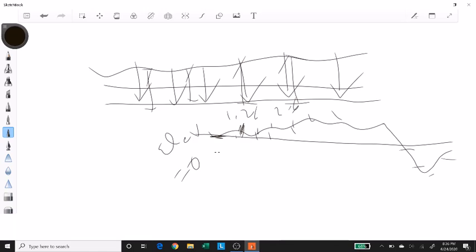And usually this reference is used as a conventional one, which is usually the mean sea level. So if I'm doing a survey in Pakistan, the water level near Karachi, that would be at an elevation of 0. And as you start going north, your elevation would keep on increasing. And you must have heard the figure that in northern areas of Pakistan, they have different heights of mountains, this much in feet in thousands, or this much in meters. So if those mountains are at this much height, there should be a reference, and that reference is usually the mean sea level. So that is where you start from.